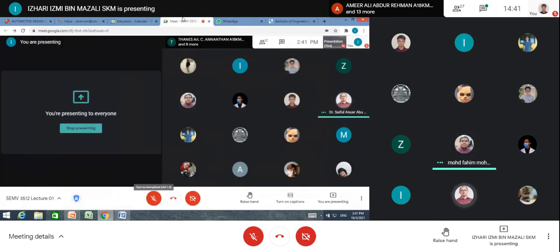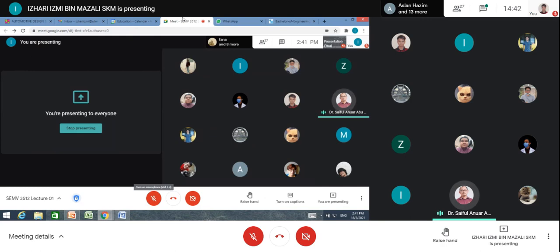Please make sure that you also install SolidWorks Motion Analysis, because in SolidWorks for motion there are three categories: animation, basic motion, and motion analysis. I want you to install up to motion analysis, not only up to basic motion, because with basic motion we cannot do stress analysis based on the dynamic load from the model. Okay, any other question?